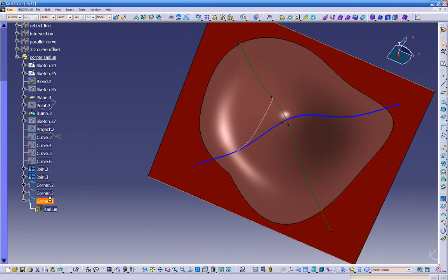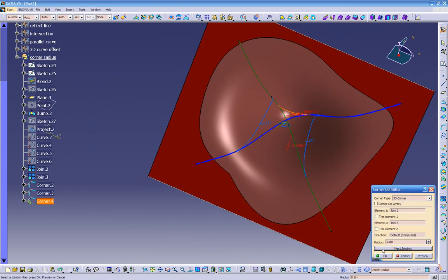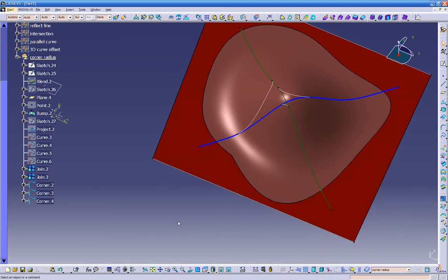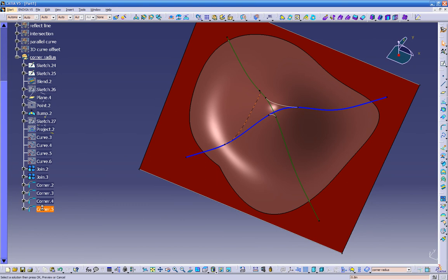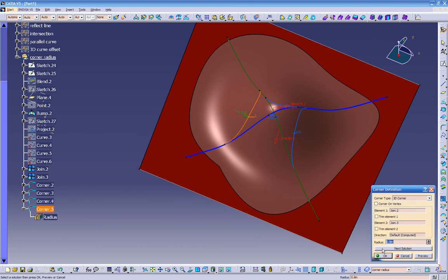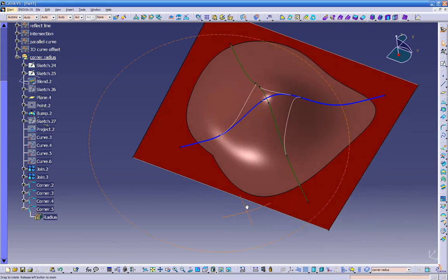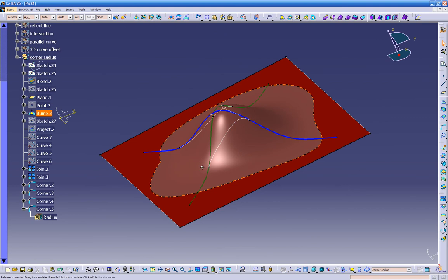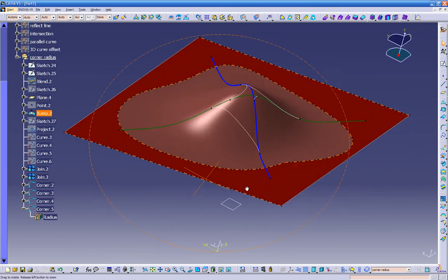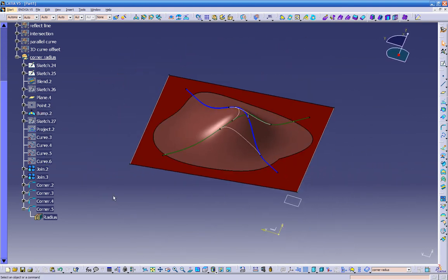Okay, let's go maybe next solution. Okay, and let's Control V again, paste the last one, and let's make sure you get number 4. Let's click OK, and now we got all 4 curves in there. So that's how this option works. Corner, it's a 3D corner.